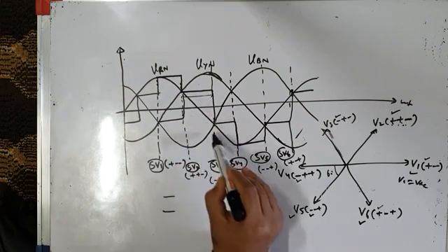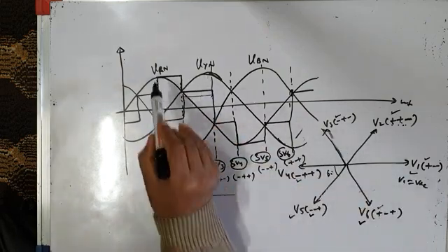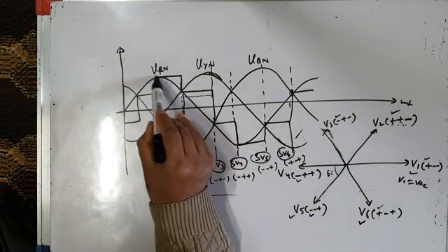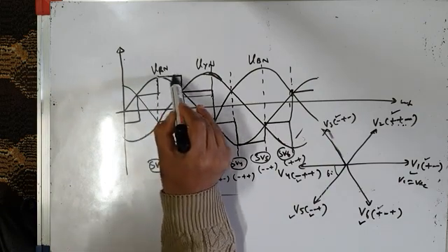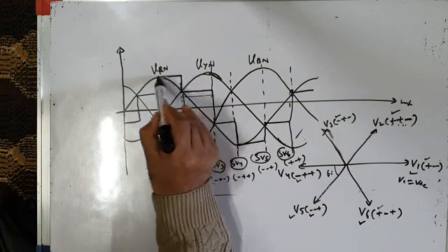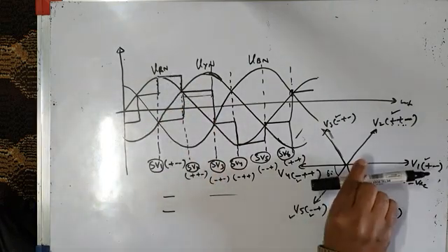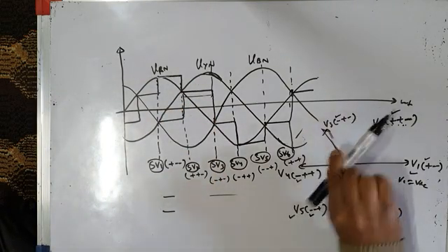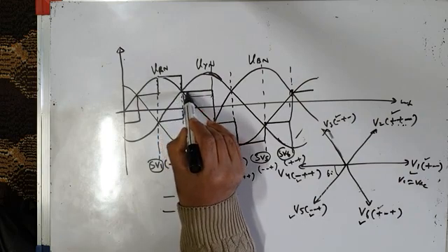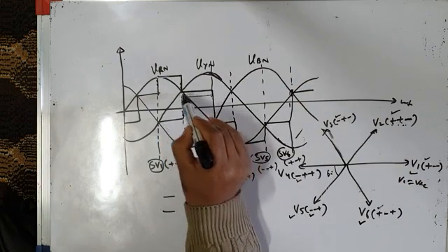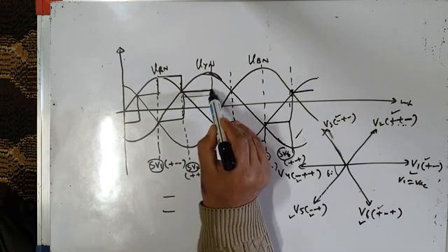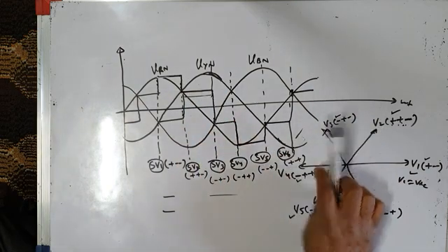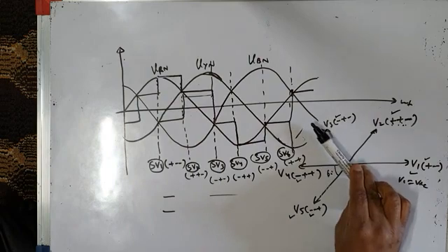Or instead of moving sinusoidally like this, होता क्या है 6-step voltage source inverter में they remain constant. For example, VRN is plus 2/3 VDC for 60-degree interval, it remains 2/3 VDC. उसके बाद आपका space vector जब V2 पे आ जाता है, so इसका value 1/3 VDC पे आ जाता है and it remains 1/3. It does not go like this sinusoidally. It remains 1/3 VDC for next 60-degree interval. And then your space vector after 60 degree becomes V3 equal to VDC.